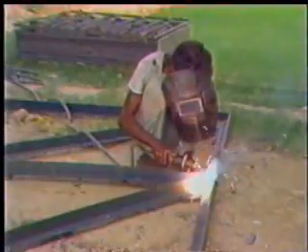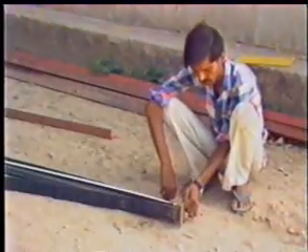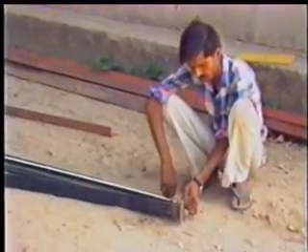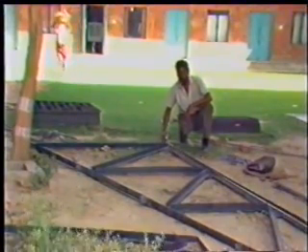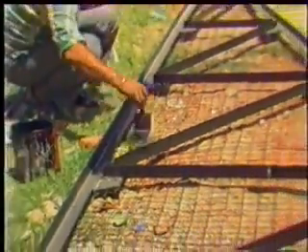Cut angles and gusset plates are then joined by spot welding as per the truss layout. During fabrication, span and other dimensions of the truss must be checked as per fabrication details. Cleats are welded at predetermined positions on the principal rafter of the truss for fixing purlins. To safeguard against weathering effects, the trusses are painted.